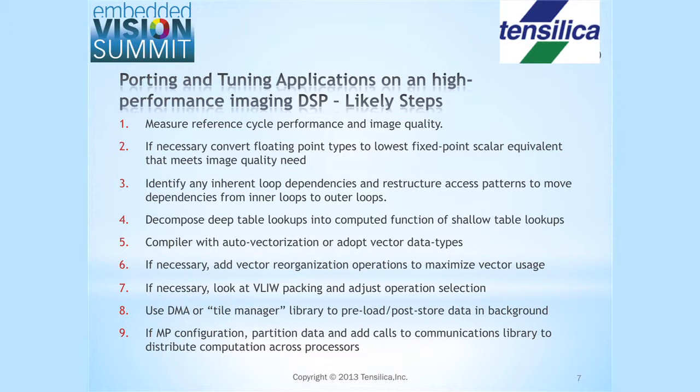Now, this is usually pretty simple in terms of image enhancement algorithms where you have very commonly unit stride access. You have to be a little bit more clever, for example, in some kinds of vision applications where you're effectively going through a region of interest filter, and the regions may become more scattered and smaller, and there may be opportunities to regather those data points together by a variety of means.